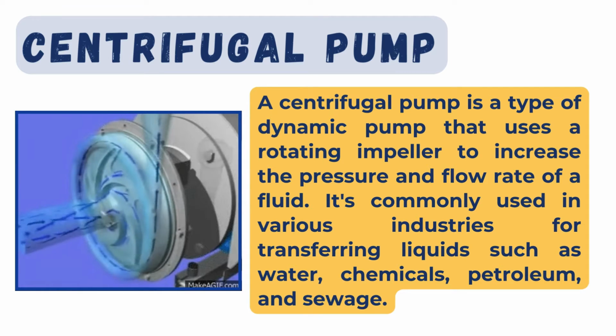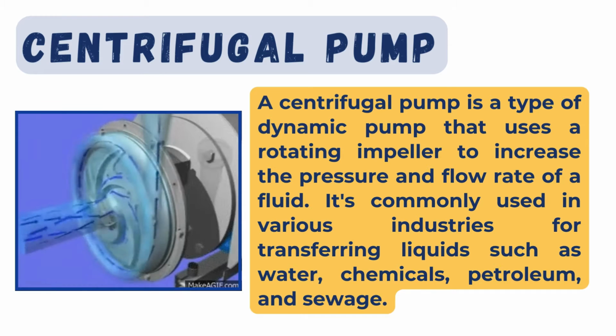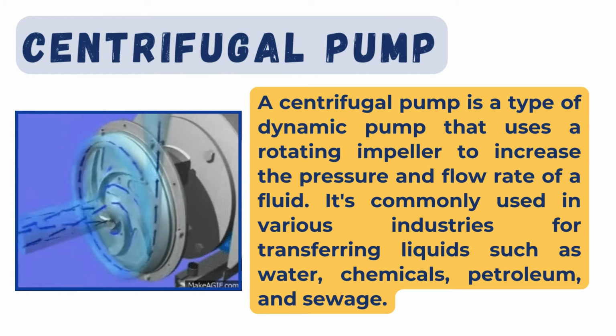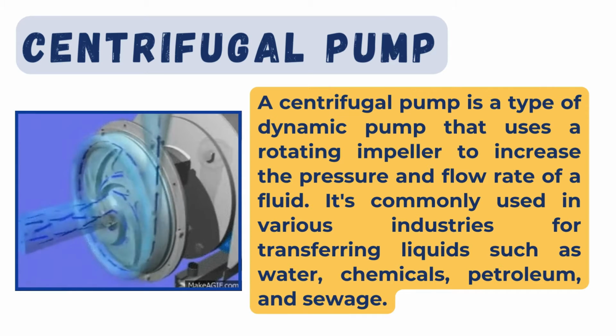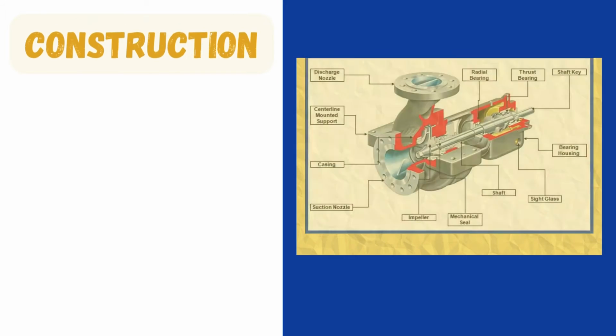Okay? So in simple words, guys, a centrifugal pump works on the principle of centrifugal force, and it is a type of dynamic pump or kinetic pump which is used to transport liquid from one stage to another, and which is done by converting the mechanical energy obtained from the motor or engine into kinetic energy in the fluid. Okay guys, so I hope the basic definition of centrifugal pump is clear to you. Now moving on with the main components or the construction of the centrifugal pump.